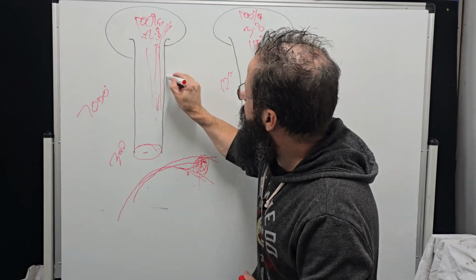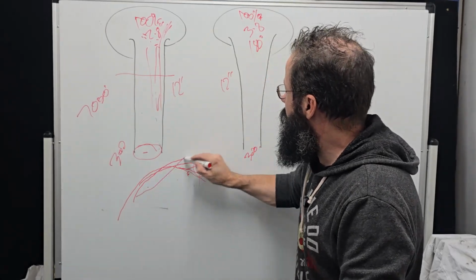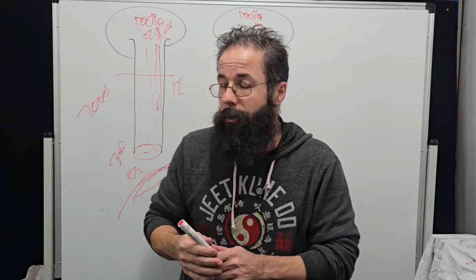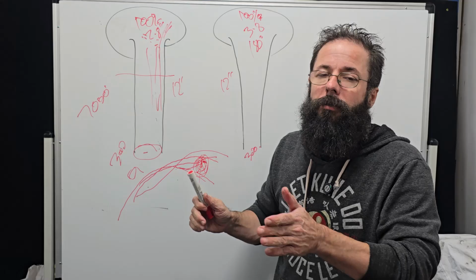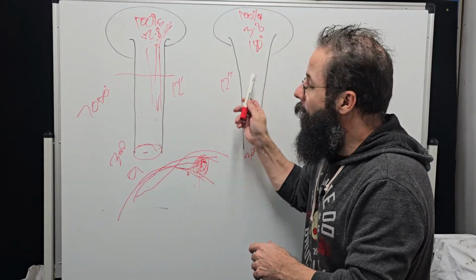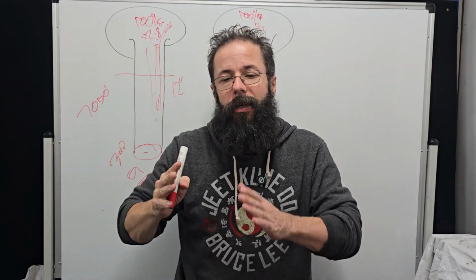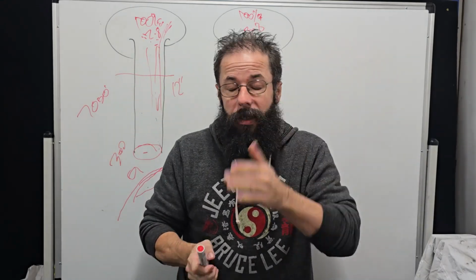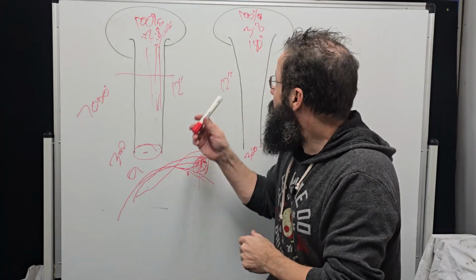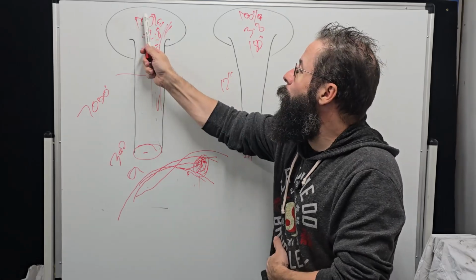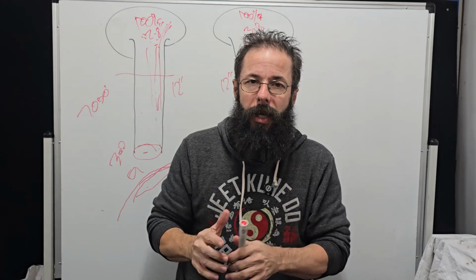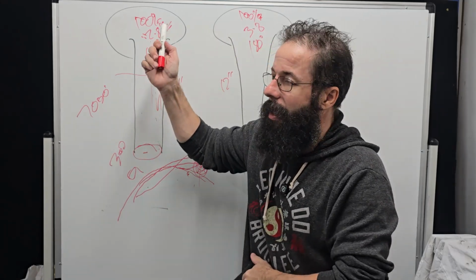So then what they do is they cut the runner down and go, oh, look, and now this one goes like that. But they've killed all their mid-range, or they've killed their torque. So again, it's not easy, but we need to look at how to optimize the length harmonically, the volume, and I'll go into a couple of calculators in a second that actually do this with different runners and tapers, and the velocity and how much we're washing out the plenum and how big dynamically that plenum looks to the engine, because this one's going to be throwing out a hell of a lot more.